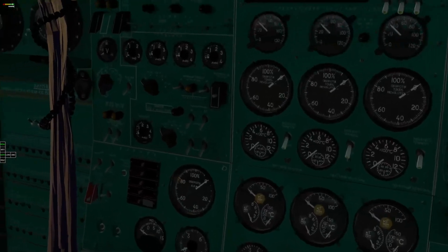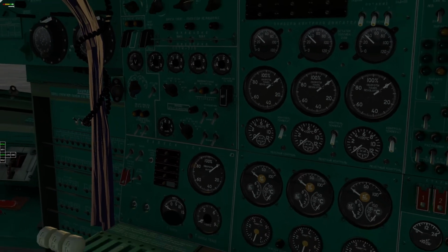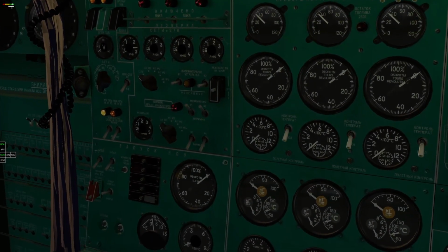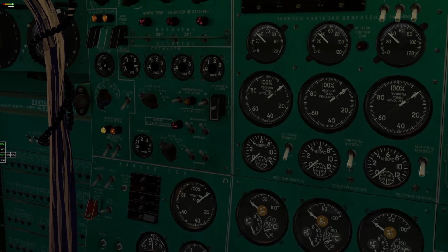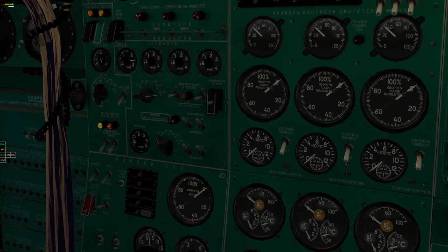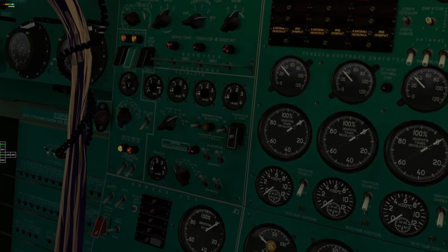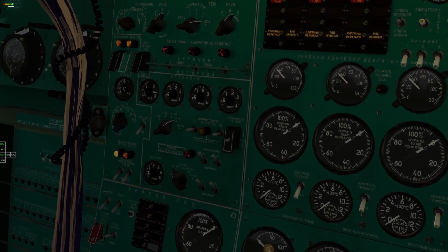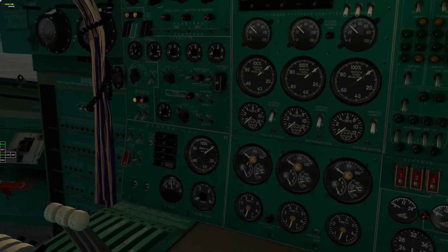To do it, first of all we need to switch the batteries on. So, number 1, number 2, 3 and 4 to the up position. We can also check the voltages of every accumulator. It should be no lower than 24 volts, but it should be 27 usually. Alright.